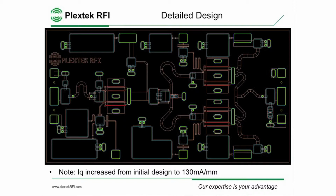We've got an inductor here, through which we're injecting our gate bias. These transistors can draw a reasonable amount of gate current, so we can't have too high a gate resistance. It's a modest gate resistance here. It's the gate bias point here, and more capacitive decoupling here.